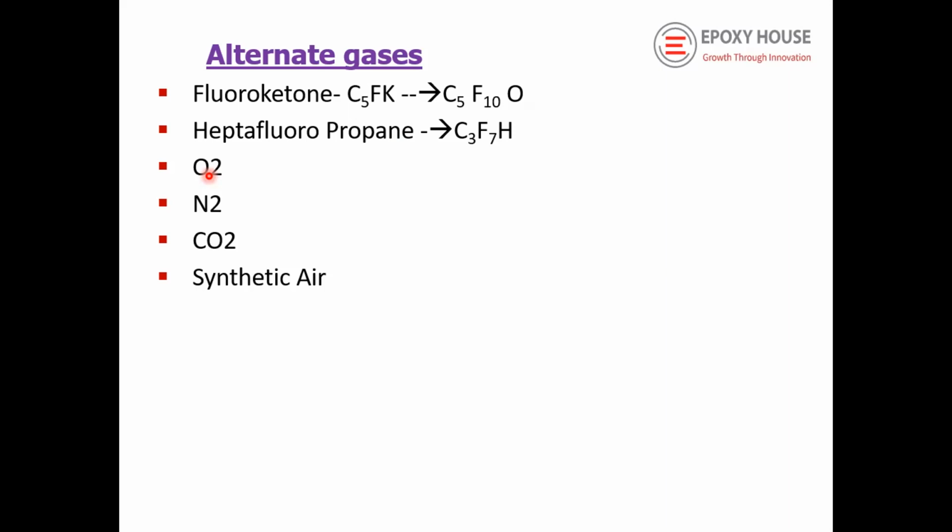So medium voltage switchgear can take a faster replacement than higher voltage, for example 72 kV and above 145 kV. The pace is slower, but it's stable. People are using the gases. So these are the other gases. Oxygen is used, nitrogen can be used, carbon dioxide is also used. Synthetic air is the purest form of it, 80% nitrogen, 20% oxygen, used as a replacement. And fluoronitrile is also used as another one.